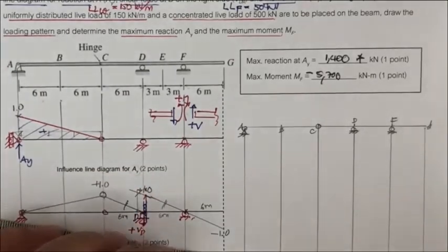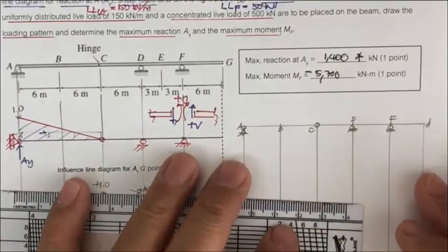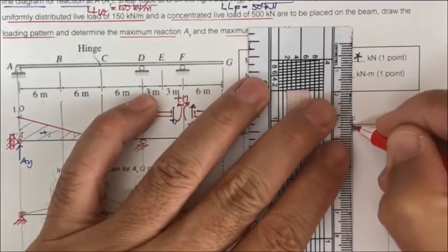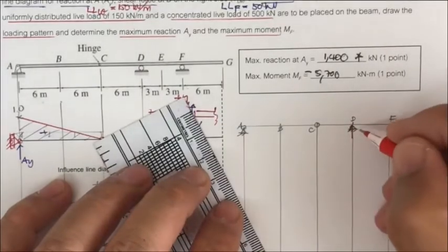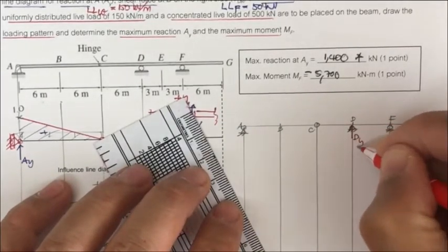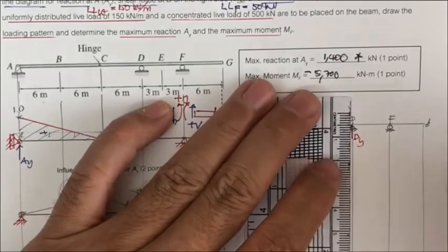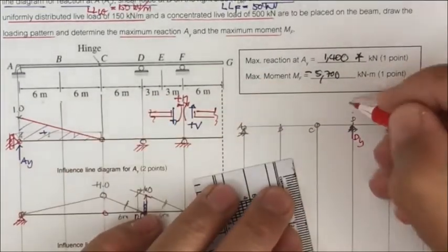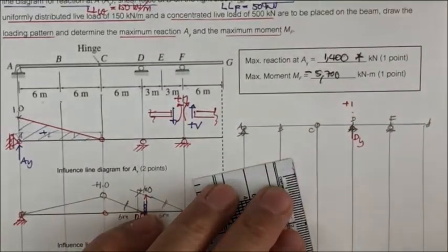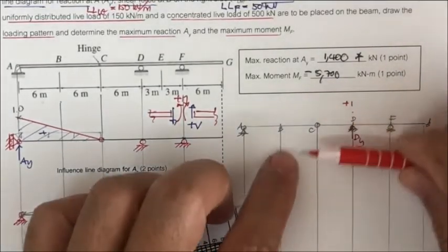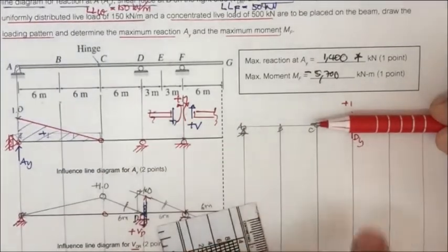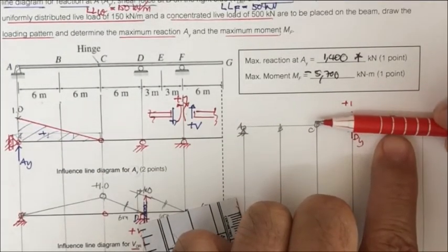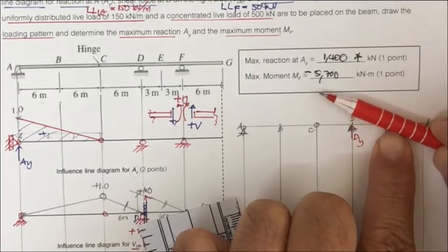If you like to draw the influence line of D sub y, you eliminate the resistance to the D sub y and put the D sub y there to move it for 1 unit. You move it for +1. And what happens is, when you move this one, this is going to be the rotating point. When it's moved, it's going to move like this, 1 unit.